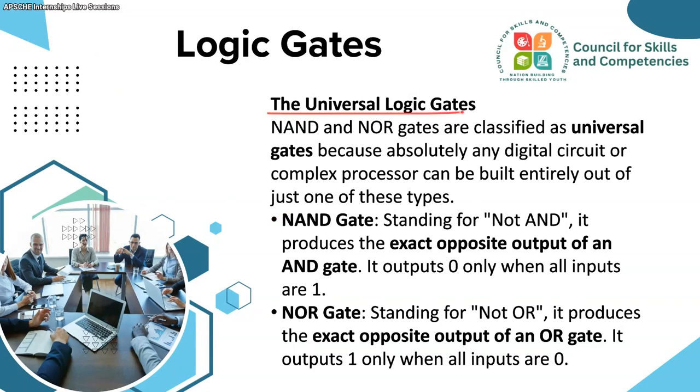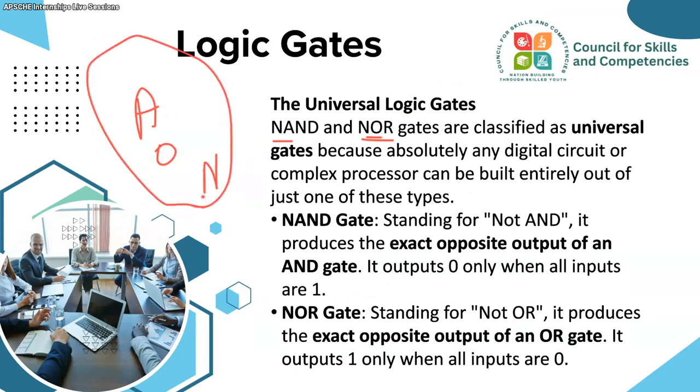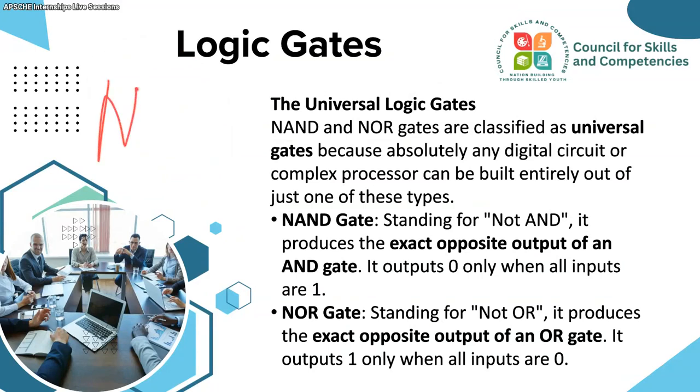There are two universal gates, the NAND gate and the NOR gate. Using NAND or NOR, you can derive the AND gate, OR gate, and NOT gate. How good. If you purchase only NAND gates, you can make any circuit.